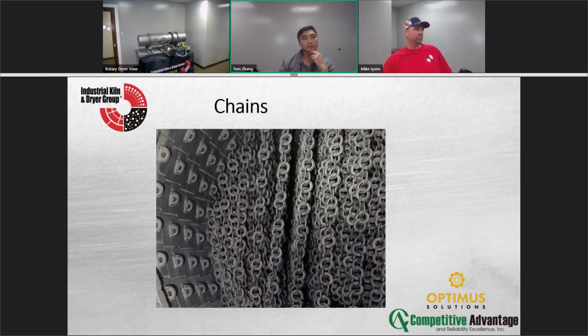Yeah, there's another question. What is the recommended maximum ovality to avoid refractory damage? That depends on your diameter. So my rule of thumb is, let's say you have a 10-foot diameter. I like to convert over to meters. So 10 foot is roughly 3 meters, right? It's 0.1% of that. So for 3 meters, 0.3% ovality is your upper limit, okay? That is a general rule of thumb that I've used that has been relatively good so far.